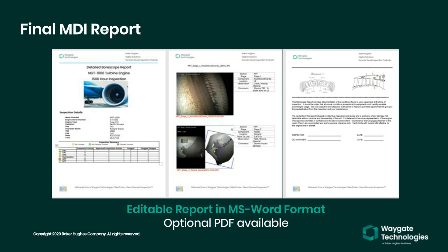Remember that an MDI does not need to be a full front-to-back inspection template. It actually could be designed to define a critical inspection point or two associated with some type of service bulletin. The MDI potentially could contain reference images showing the orientation characteristics of the view of a component at an inspection point for which the author of the MDI would like to have captured.